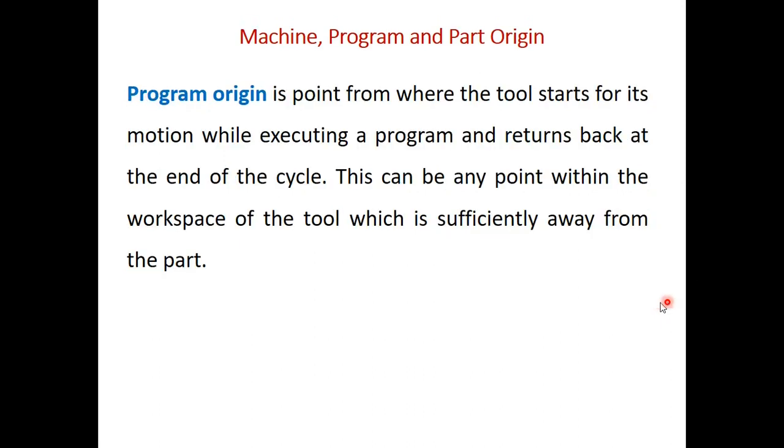Next is the program origin. Program origin is the point where the tool starts its motion while executing a program and returns back to at the end of the cycle. This can be at any point within the workspace of the tool which is sufficiently away from the part. So program origin is defined by the user.